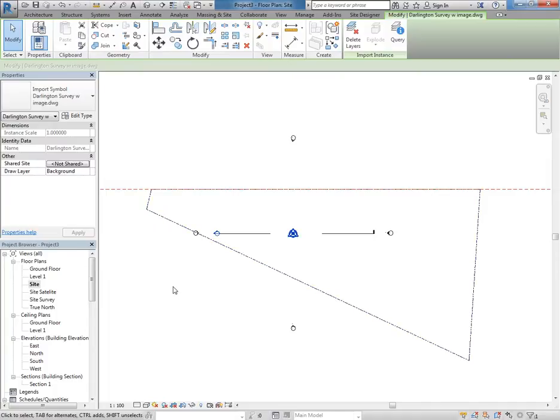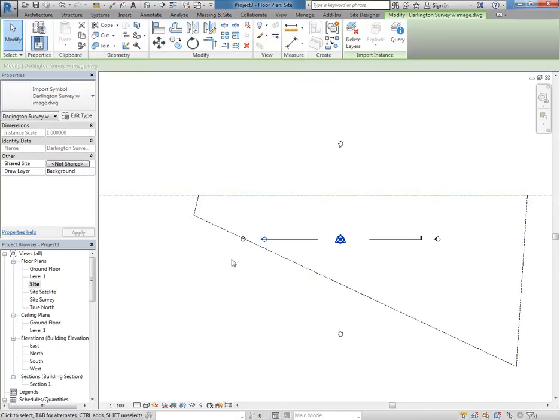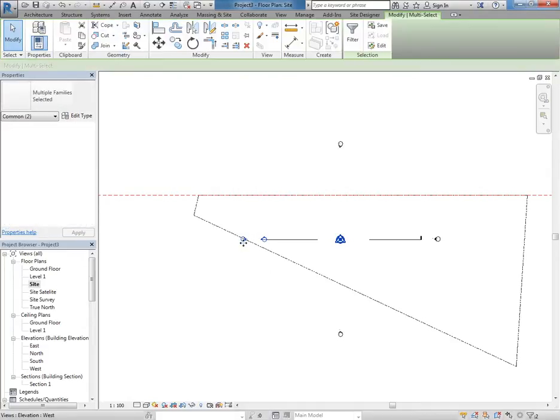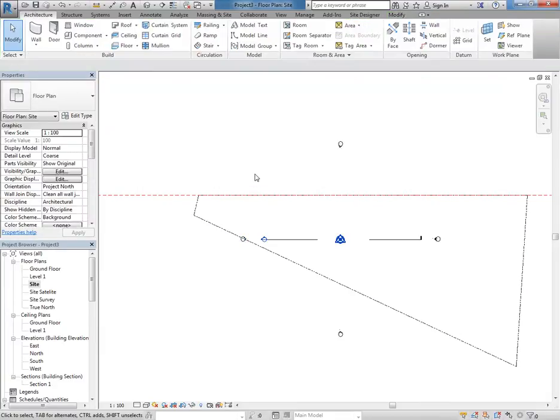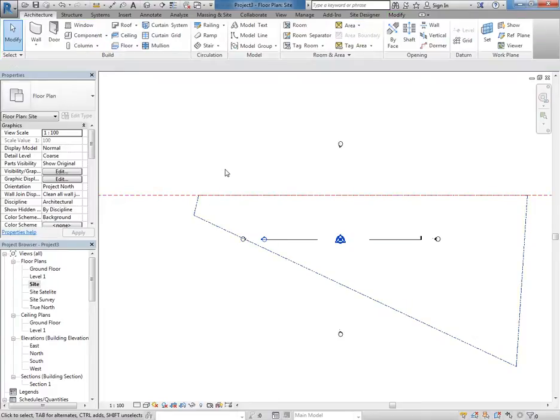So now all I need to do before maybe, well, I'll give you a break as well, but you can also have some time to work on this. I'm going to make a window left to right to select the elevation views. So if that's not clear, if I was to do it right to left, notice how it gives me a dashed line when I click and drag, and that's going to select the things inside that window, but also anything it's touching. And that means it will select the boundary and the reference line or reference plane and maybe some other things. I don't want that. So I'm going to make a window left to right, which will only select the things inside the window, not the things that it touches.